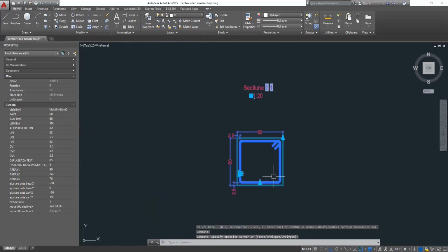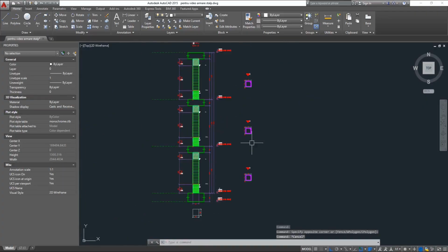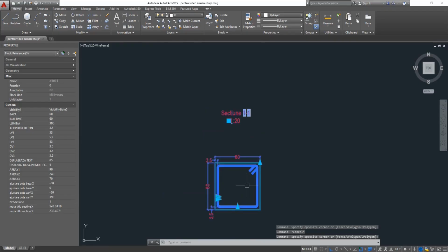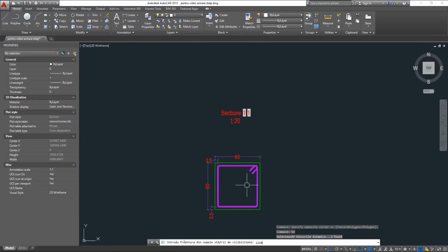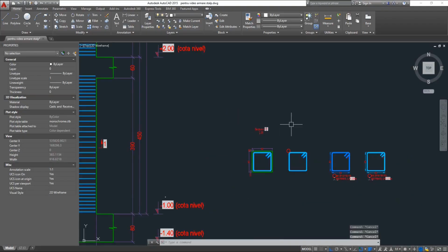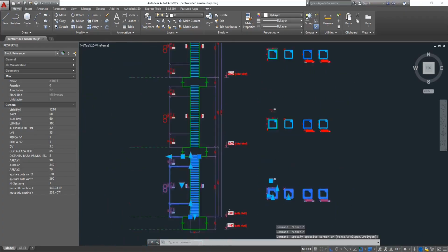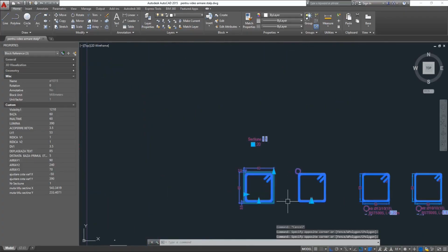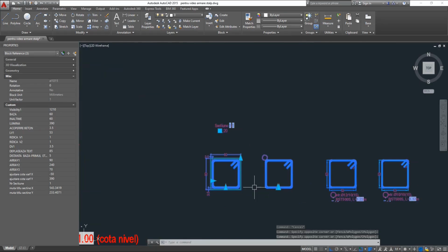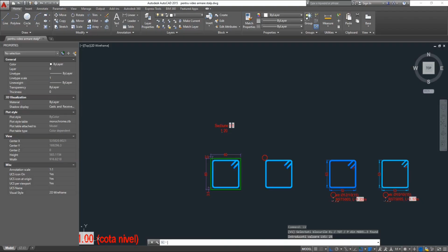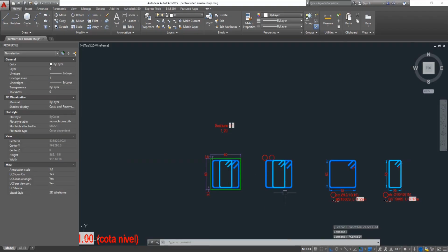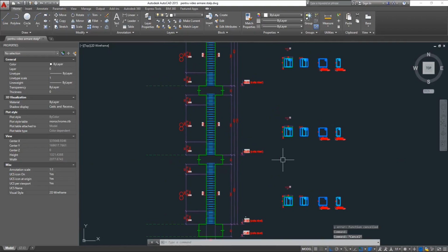And now we're going to change the diameter. We're going to choose two kinds of stirrups, a 12 and a 10 millimeter. Okay, and we choose to have on all levels the intermediate vertical one with a width of 25 centimeters. And it adjusted.